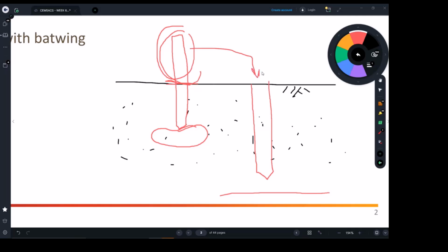Yeah, that's what they use. You can actually use multiple pieces on top of each other, just kind of nailing into the ground. You want to make sure this will have adequate bearing. It's going to get refusal, adequate friction on the side, I should say, and adequate bearing at the bottom. Then when you get that refusal, you will saw cut, or you keep hammering down if you did not.